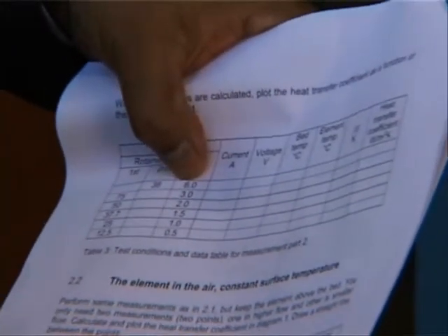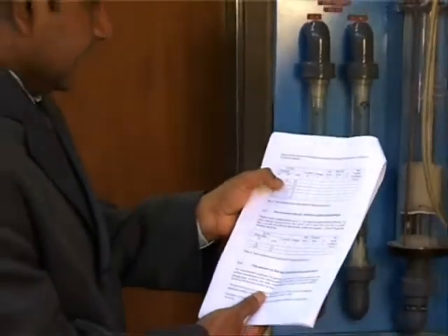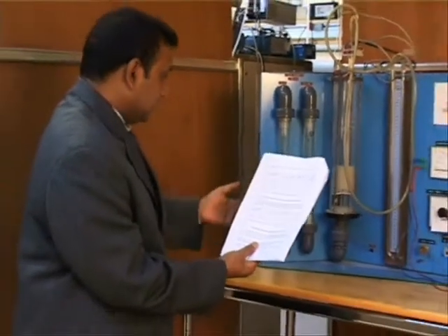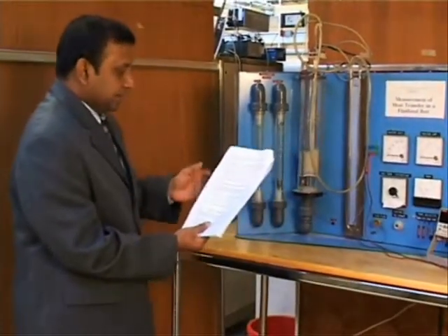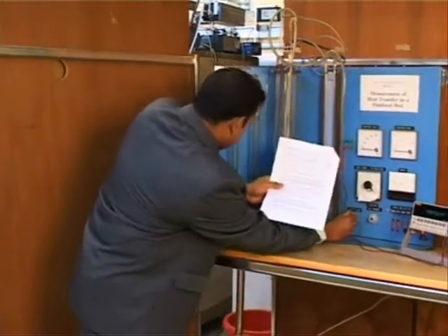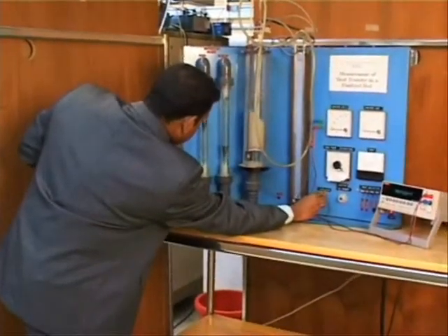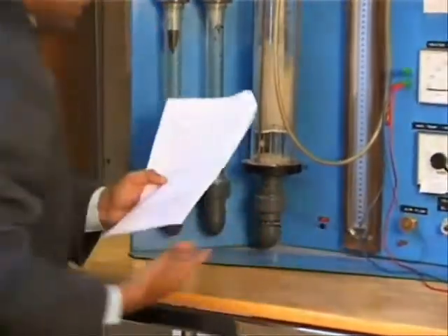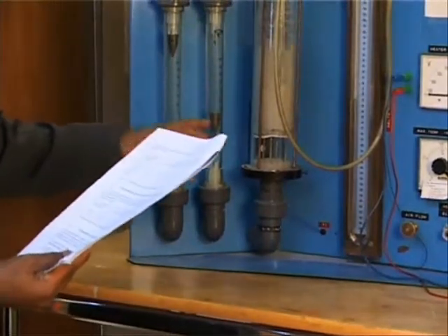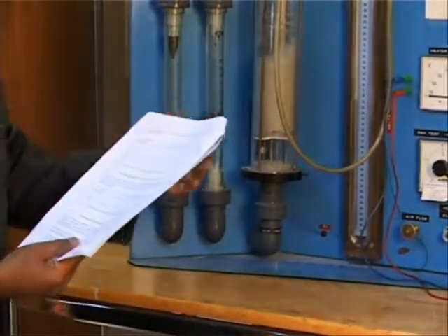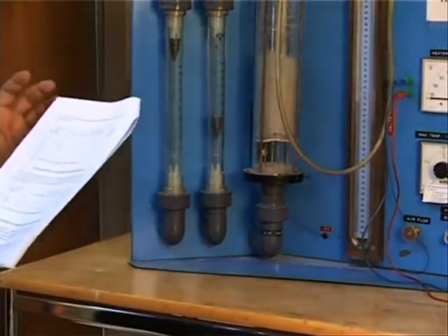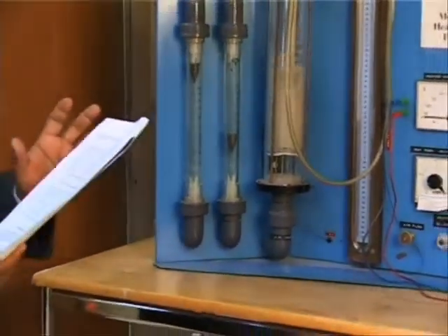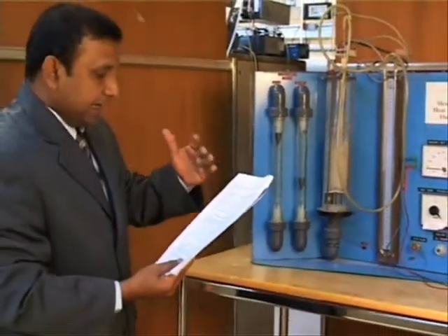To get this 6 cubic meters per hour of air flow through the reactor, you are supposed to set 38% on the second rotometer, which is defined by our previous calibration. So I increase the flow here to get a 38% reading on my second rotometer, which corresponds to 6 cubic meters per hour, and then I'm trying to calculate the heat transfer coefficient at varying flow conditions.